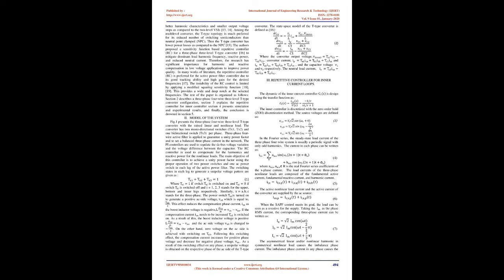Different researchers have investigated different configurations using the passive filter, star-delta transformer, zigzag transformer, single/3-phase active power filter, and a combination of the above [5, 6, 7, 8, 9]. The passive filter has been proposed in FBD with resonance LC filter branches for dominant positive/negative sequence and zero sequences. The passive filter has low cost and is simple to implement with the system. However, the passive filter might lose its tuning performance at the target frequency due to component aging, and creates series/parallel resonance with the system inductance [10].